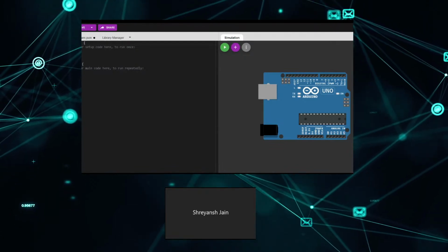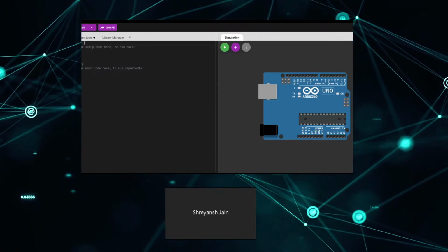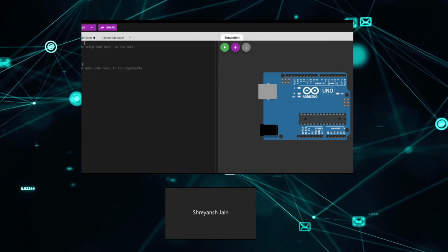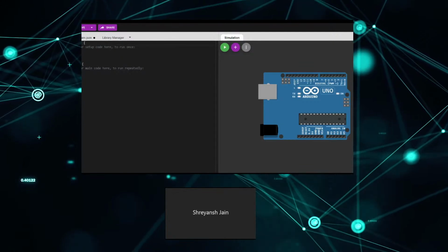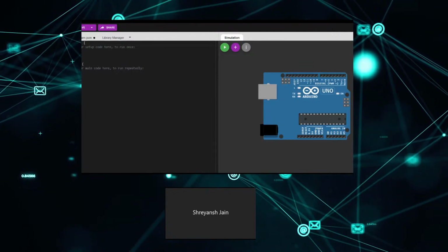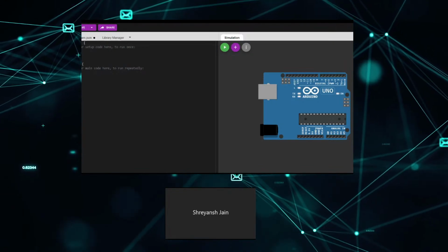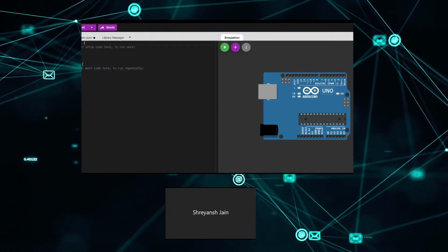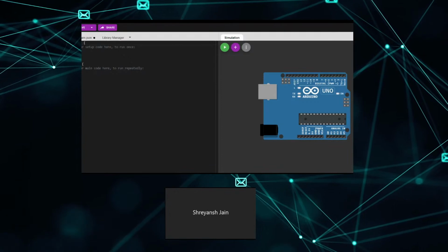So in the Arduino program, we will need the distance between the closest person and the door, and we'll need a sensor for it. We need to sense the distance. If you recall from your previous sessions, we can use an ultrasonic distance sensor for it. Once we have the distance, we can check if it is more or less than 50 centimeters, and depending on that, we can control the door. To control the door, we'll also need a servo motor. And that's the basic overview of the project.